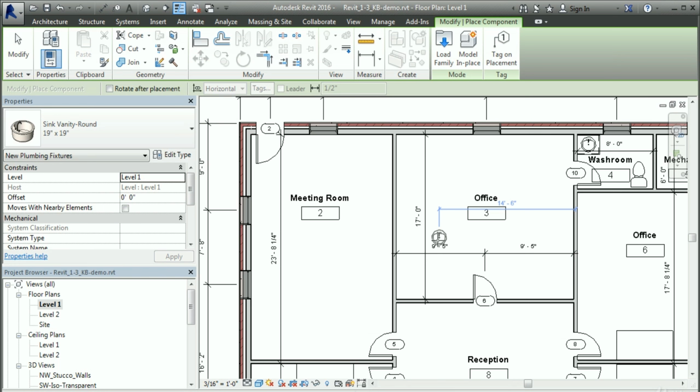Now, it would be possible to load one of those rectangular or elliptical or dining room tables and then create a new type. Just make oversized dimensions to generate a 12-foot version. And we can even rename the family by finding it in the project browser and then renaming it. This would be a good practice exercise, and if you'd like, you can definitely try that on your own. But we're going to bring in a table from Autodesk Seek instead.